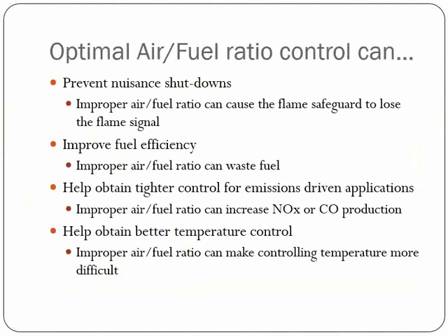Some other systems or control valves take a large step change to make a big jump to physically move the valves, and there we'll see a larger temperature fluctuation in the process. Sometimes it's not as critical, but for other applications where compliance is an issue and extremely sensitive, having the proper air-fuel ratio control makes all the difference.